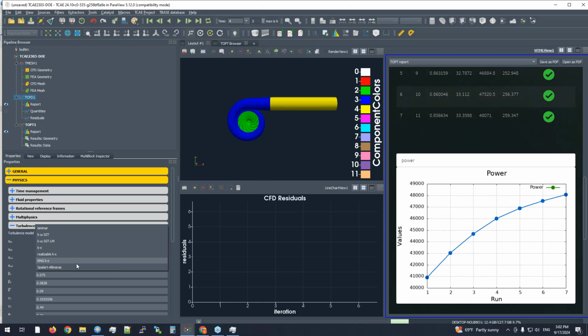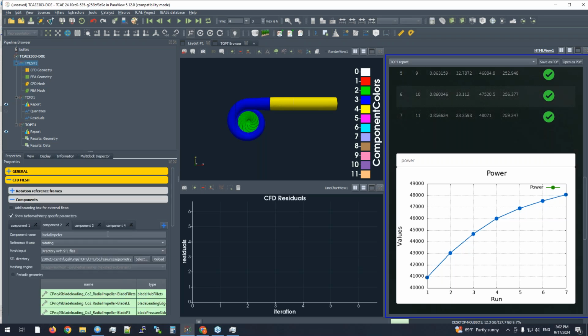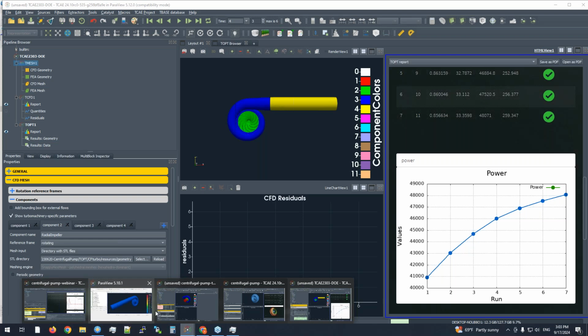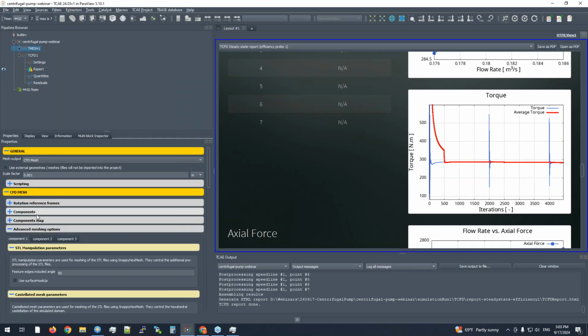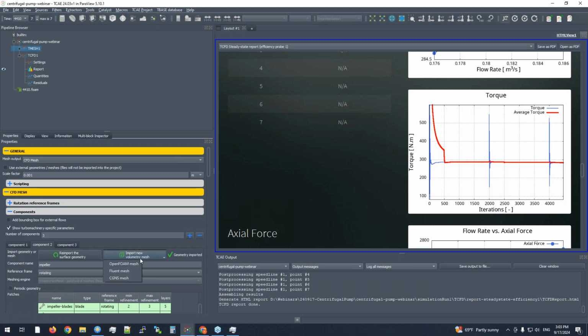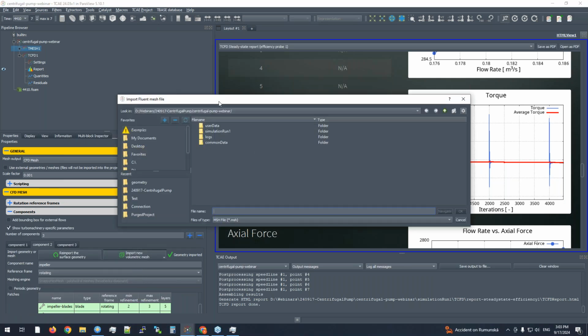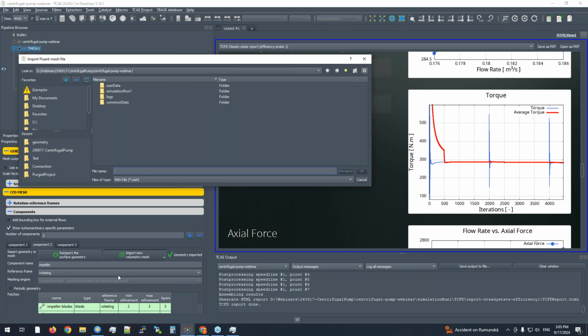Nicholas is asking about the possibility of external mesh, but I think it was mentioned during your contribution, Radek, right? Yes. I mentioned it, maybe I was too quick, but you can import. Let me show you. If I go back to one of our example T-mesh components, here you can import a volumetric mesh in a given format. You will locate it on your disk. It will be automatically loaded and can be used for the simulation directly. And as I said, you can also combine different volumetric meshes with the STL import, for example, of another component.